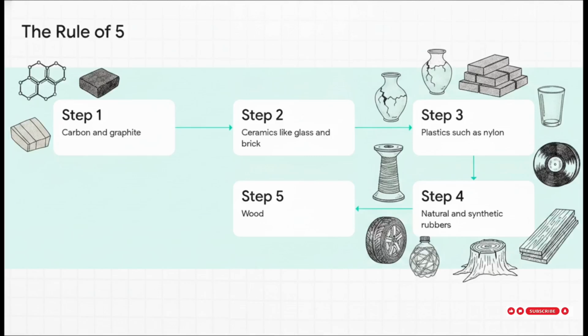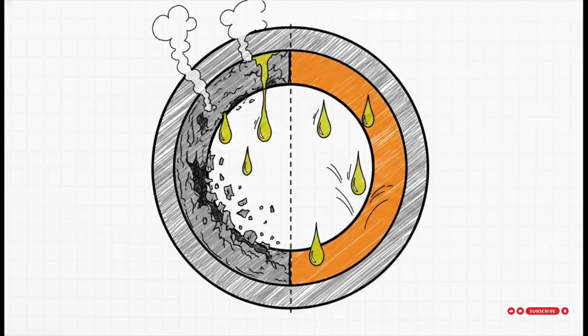Basically, if it's not iron-based and it's not another type of metal, it is going to fall into one of these 5 non-metallic categories. But why do engineers actually rely on this third folder? Well, often it really comes down to survivability in incredibly harsh environments. These nonmetallics are frequently deployed for integral monolithic construction or as super thick sheet linings to solve severe corrosion problems. Think about chemical plants or highly corrosive settings where cheaper materials like standard steel would just rapidly degrade and fail. A thick lining of synthetic rubber or specific plastics, however, totally stands up to the challenge. It really proves that sometimes the absolute best engineering material isn't a metal at all.